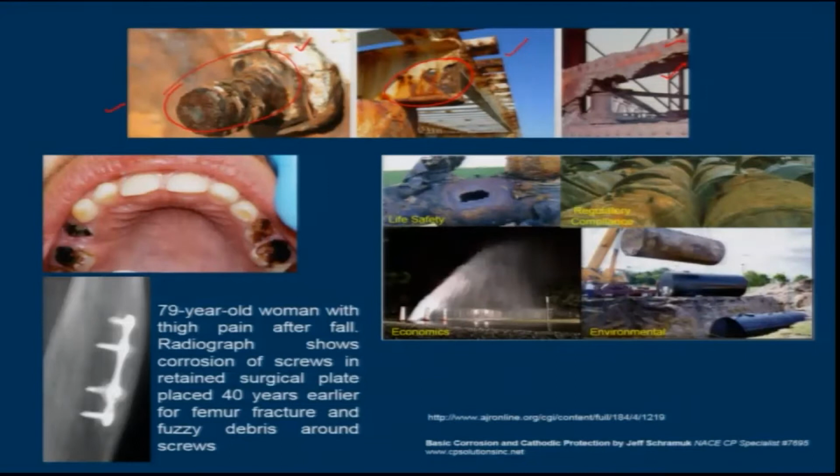You can see that the entire material is eaten away, and the thickness this beam initially had has reduced, this particular section has reduced. That means initially it was designed to carry some load. Now since the cross section has reduced, of course it will not be able to carry that load. At some point of time it will definitely fail, and when a metallic structure fails, it fails catastrophically without giving any signal that it is failing.